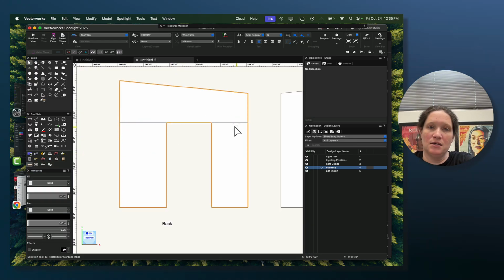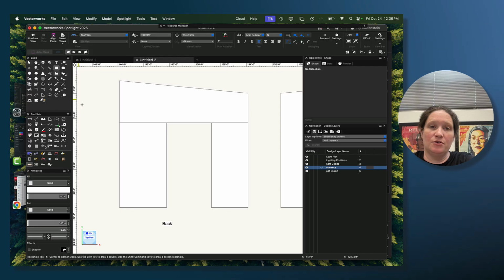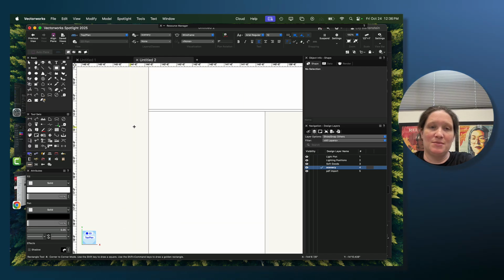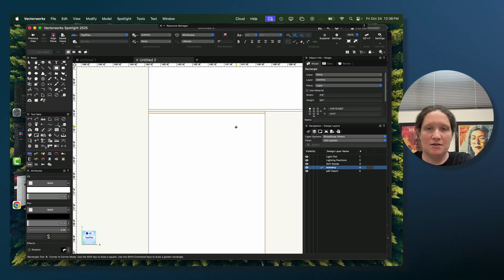So there's that. Now I want to make another little rectangle on the bottom side. So that's going to be like the rail of this top trapezoidal flat. Make a piece here. As I slide my cursor over, when I get to the other side, see how it kind of snaps into that object? That is going to automatically determine the width. So I can hit tab, it's going to snap to that. I can just hit tab over from there and say minus 3/4 of an inch. That's going to be the thickness of that framing piece that sits underneath it.